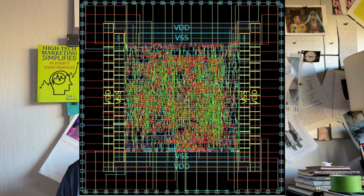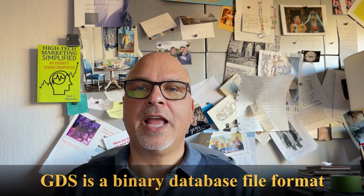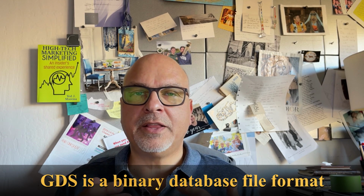After you have your design done and you've simulated it, checked it out, made the changes, and you're ready to move forward, you then place and route the design. That depends on where you get it manufactured, how it's done, what tools you use, and so on. This is basically the last step before it's manufactured. You run place and route, you create what's called a GDS, and that file is sent to whoever is going to build the device, and then they go and make the chip.